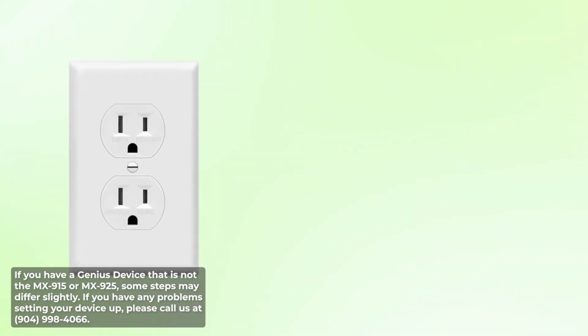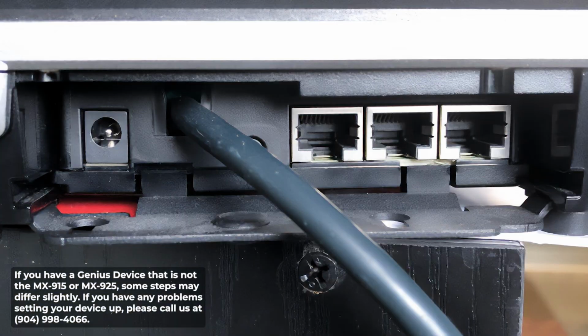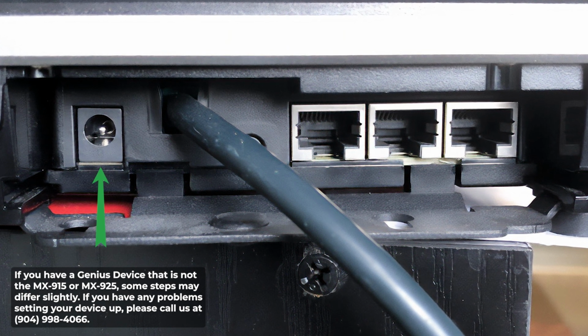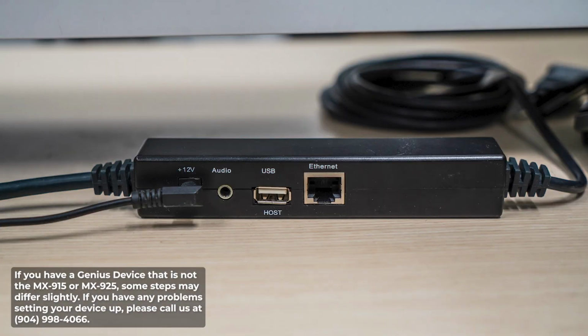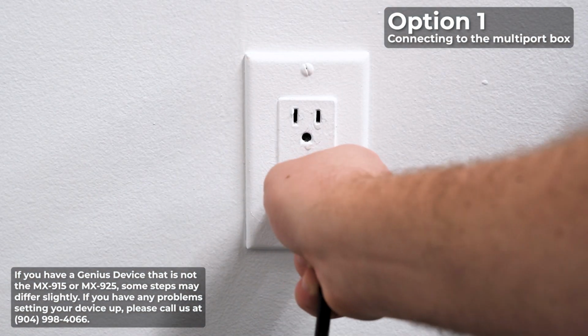Notice that the device will need a power outlet and a Cat5e or Cat6 Ethernet connection to the network. The device itself has Ethernet ports and a power jack connector. Also, there should be a hardwired cable that runs to a multi-port box shown here. Plug the Cat5e or Cat6 cable into the Ethernet port and the other end to your network device. Plug the AC adapter into the connector, then plug it into the electrical wall socket.